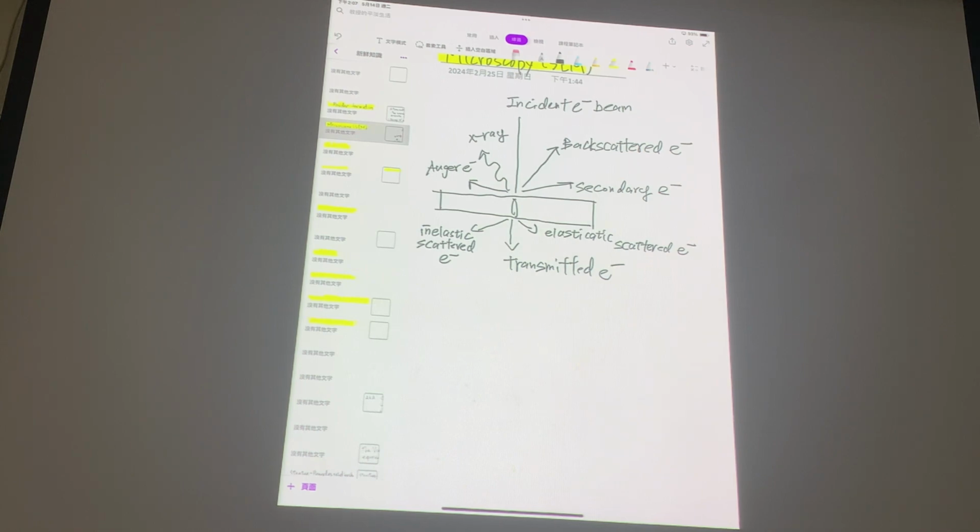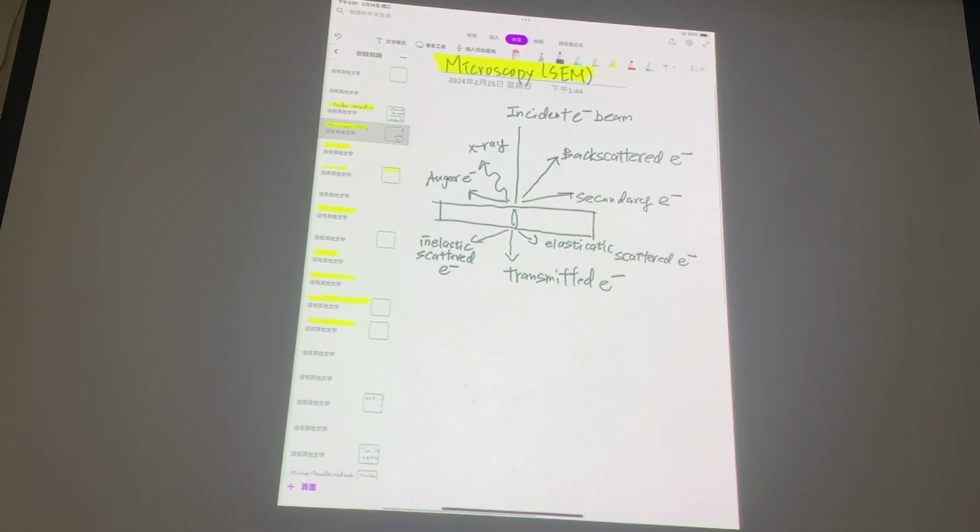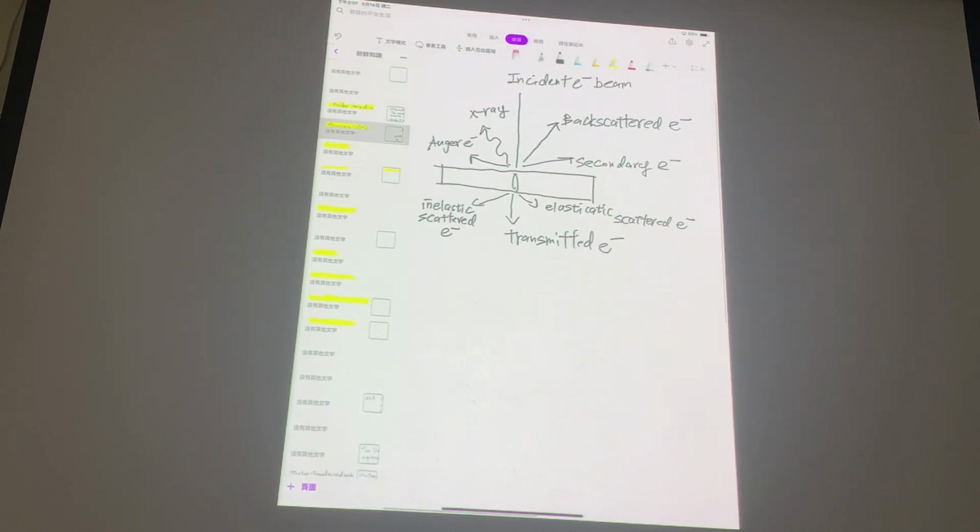Because you're getting a semi-quantitative analysis from EDS, right? So I'm going to do another drawing, a schematic, to help you remember this information. So again, think about it: I'm trying to zoom in, you have a condensed or concentrated electron beam. You can think of that as your SEM beam.